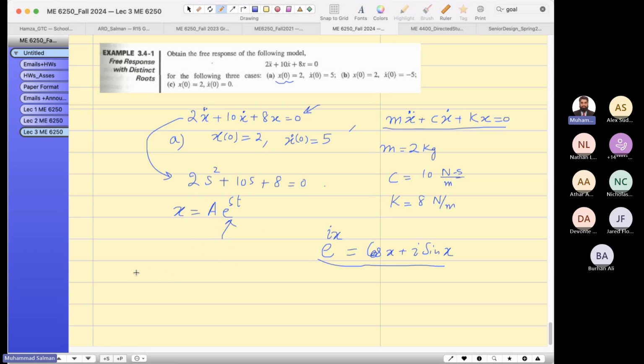So if I go to MATLAB, I can plug in this function, using the coefficients in the descending order of the degree. First, you write down the coefficient of the highest degree, which is s square, in this case 2. Then comes the second highest, then the third highest. So if I plug it in MATLAB, let me see what I get.